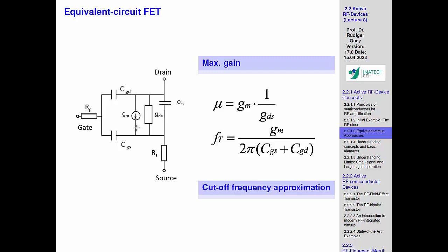You can build a simple ring oscillator, just feeding the output to the input, and see at which frequency this happens. And this gives you a time constant for such a FET. And in the first order, this time constant which you then get is the inverse of this cutoff frequency. So it relates very much to something you might have seen before. Yeah? So it's just what the digital circuit of the same transistor would do.